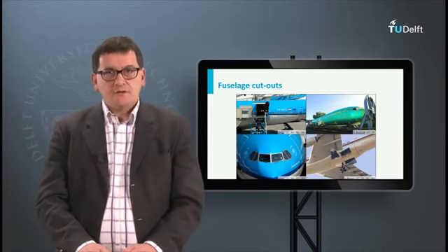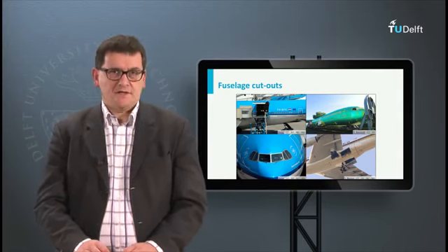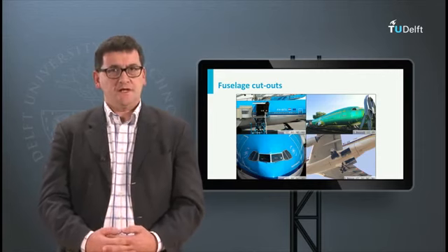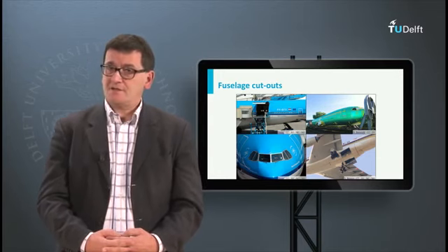Every cutout creates stress concentrations and increases the local stresses. In order to stay below the maximum allowable stresses, the skin has to be reinforced locally. The skin thickness has to be increased.